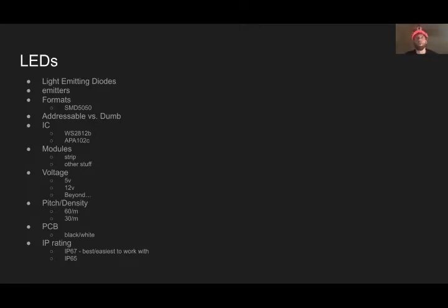If you want to remove this silicon putty in order to access the circuit board, to make a repair or do some soldering or splice two sections together, you will have to go to an extra step of scraping it off quite diligently with a Stanley knife, for instance. And that creates a mess and it's time consuming. This hat happens to be the IP65 version. But ideally you want to be working with IP67.